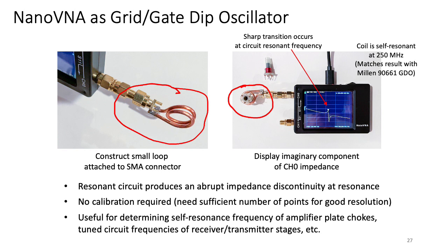No capacitor applied to it, so you would not expect a very low resonance, but it turns out that there is a self-resonance that occurs on this particular coil, and we can see that right here. If you plot S11 as a real and imaginary component, you will see a sudden, very abrupt change in the impedance value as a function of frequency.